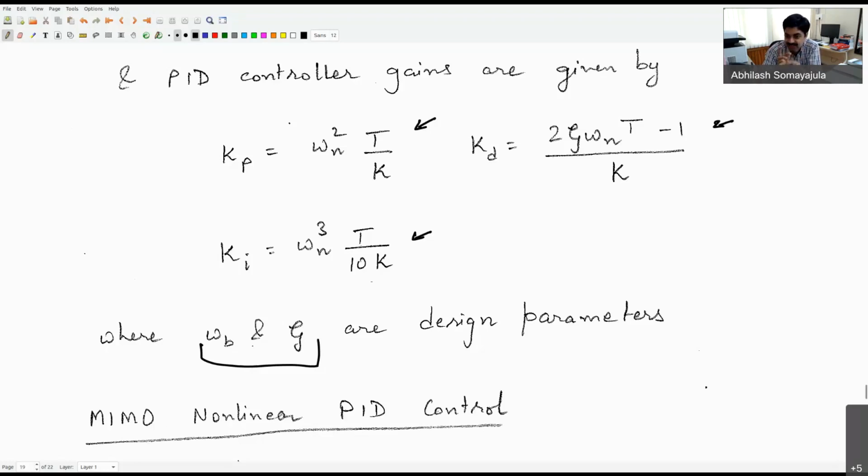You'll actually see that the so-called modeling, which we spent a lot of effort on to figure out our Coriolis matrix and all those different matrices, comes in very handy. In fact, we'll show that the Coriolis matrix being skew symmetric will help us take certain advantage in designing this nonlinear control law. And we'll be using Lyapunov methods to demonstrate that this PID control law that we'll come up with will be globally asymptotically stable. So brace yourself. In the coming lecture, we're going to start discussing that.